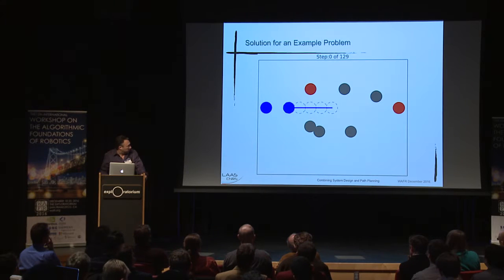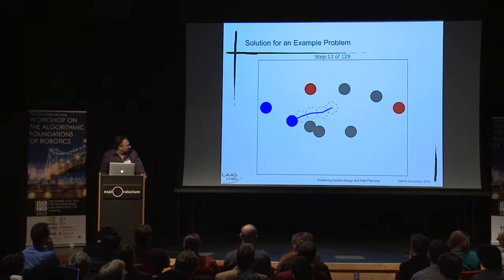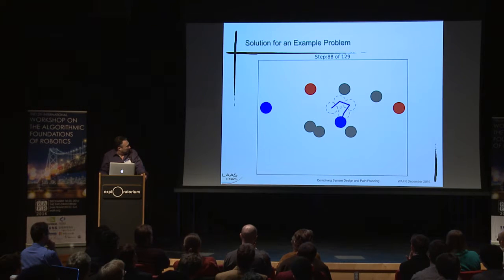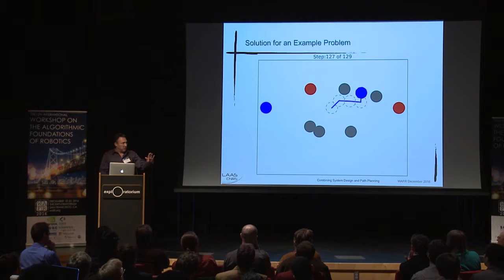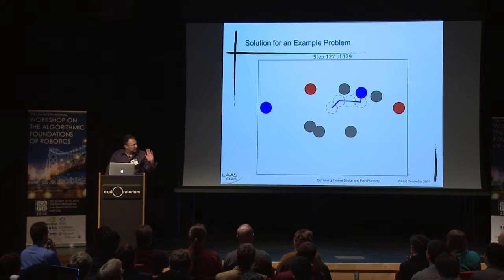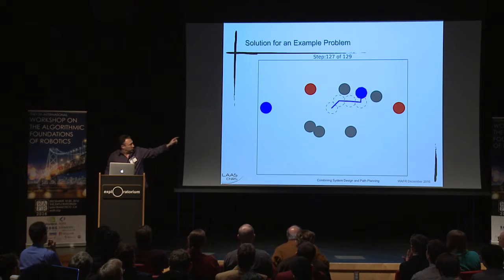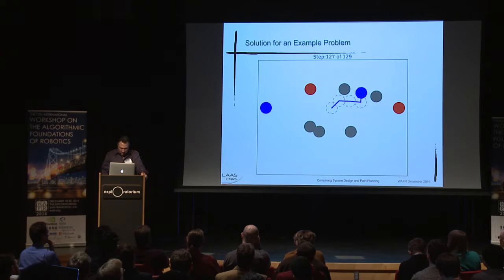Just to give you a visual example, this is a 5-body problem that we actually worked on. And you can see here, as the mechanism moves, it's a rather cluttered workspace, that the end effector there is negatively charged, and it wanted to stay near the red obstacle that's shown there. But as it moves into the goal position here, you may notice that it turned 90 degrees away from where it was. You can imagine as it got close to the red obstacle there at the end, it would get trapped in a local minima. This would increase the cost of it getting out of it.